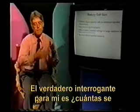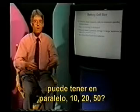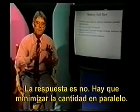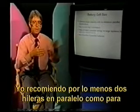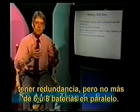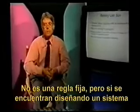The real question for me is, how many can you have in parallel? How big of a number can you go to? Can I have 10, 20, 50 batteries in parallel? The answer to that is no. You want to minimize that number in parallel. So a guideline that I'd like to give you is to have perhaps at least two parallel strings so that you have redundancy, but no more than, let's say, 6 or maybe even up to 8 batteries in parallel, but no more than that. It's a rough guideline. It's not a rigid rule.